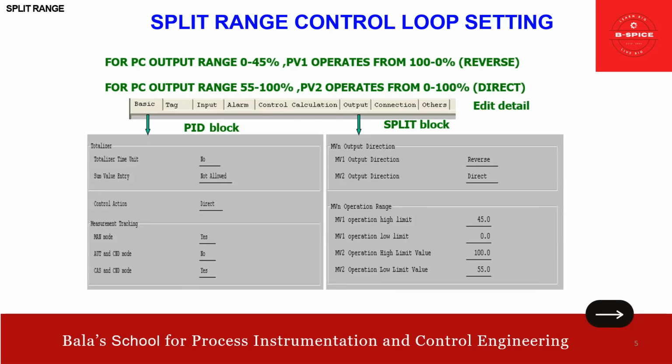Basically, PV is the process variable which we measure, friends. MV is the variable we manipulate to control the process. For example, PV represents the measured variable in a process. It is basically the actual value we measure during the process, like pressure, temperature, all these. If you are controlling the temperature of the fluid in a tank, the temperature of that fluid will be the PV. The PV is transmitted from the sensor to the controller, providing real-time information about the process state. That is the PV.